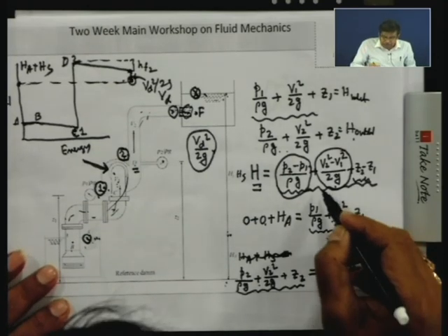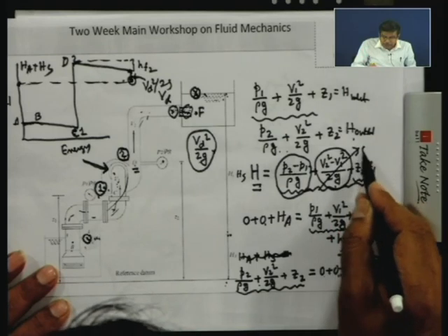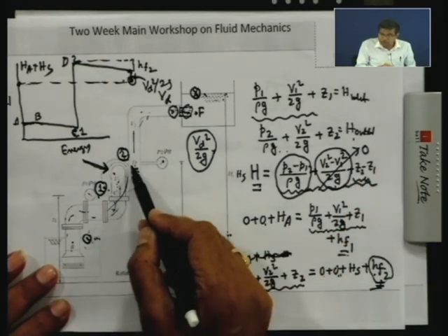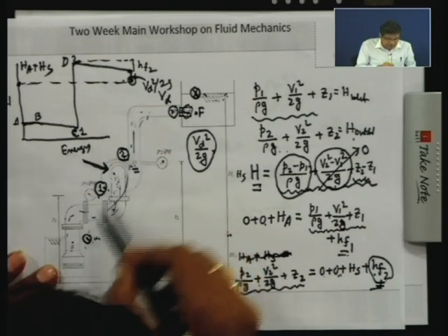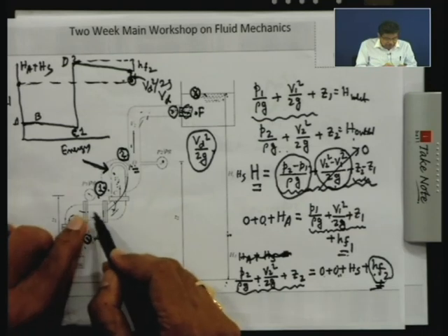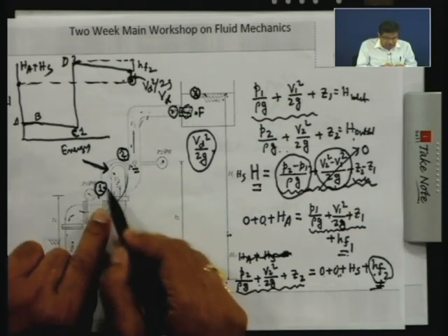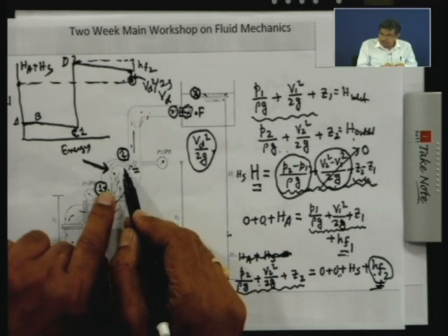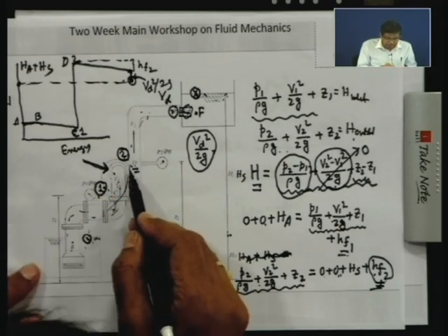If we consider the velocity at inlet and outlet of the pump to be almost the same, because of the same cross-sectional area of the pipe, then the fluid comes in with low velocity, gains energy and high velocity, which is converted by the diffuser vanes and volute casing to pressure, and ultimately leaves with low velocity.